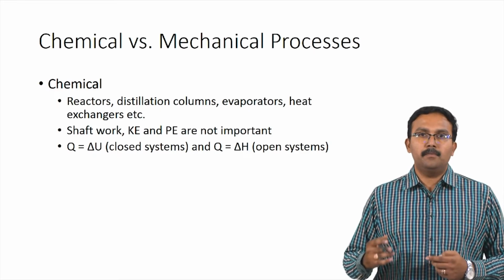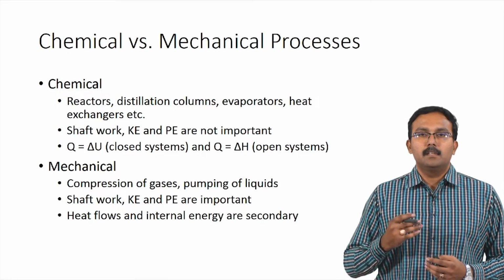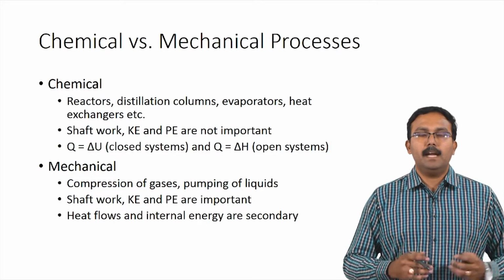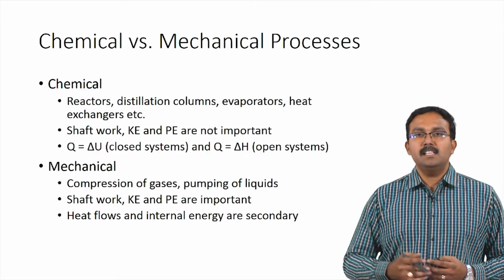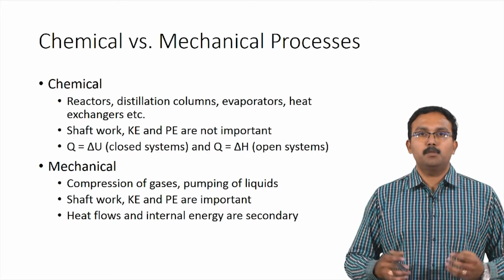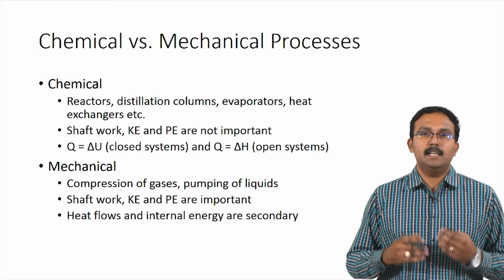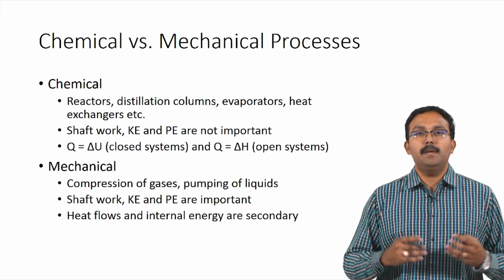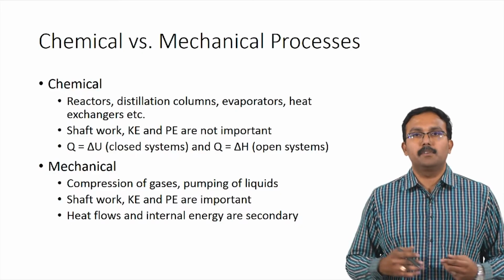There is another type of process which is called the mechanical process. Processes like compression of gases or pumping of liquids are mechanical processes. Here, shaft work, change in kinetic and potential energies are much more crucial. Heat flow and internal energy changes are secondary. This is because here usually there is not a big change in temperature. There might be some change in temperature, but that is not very significant.